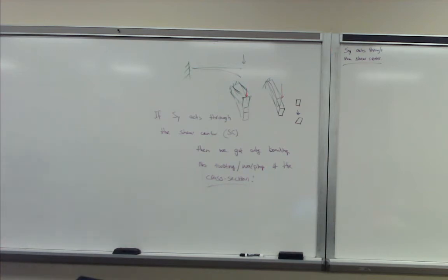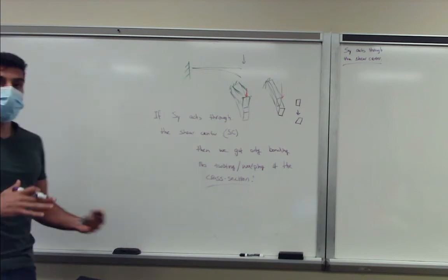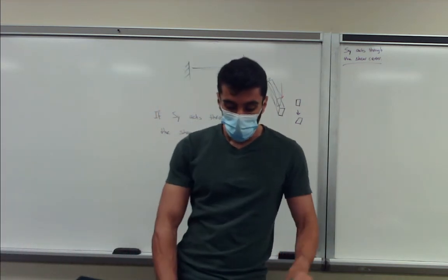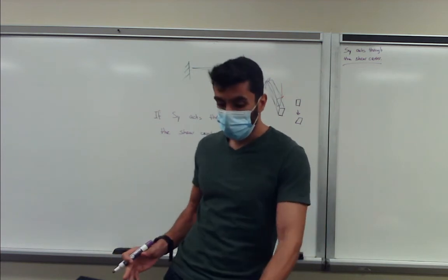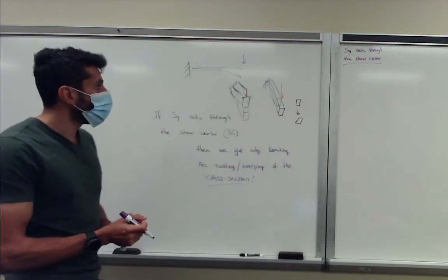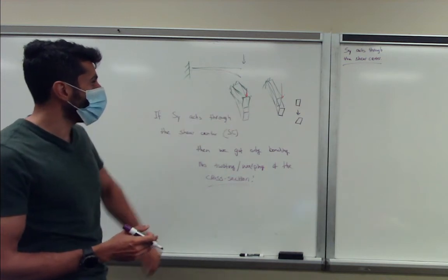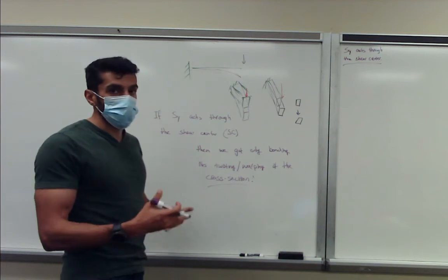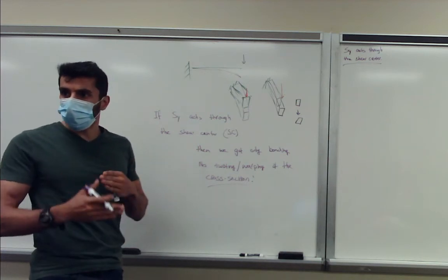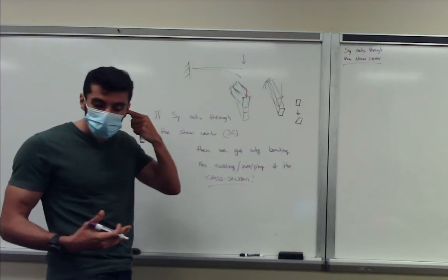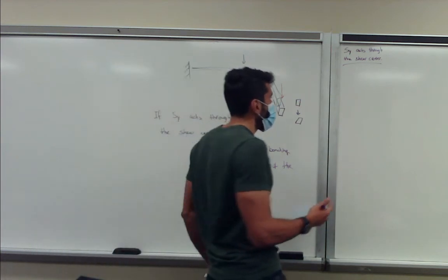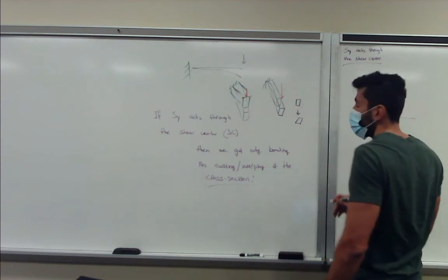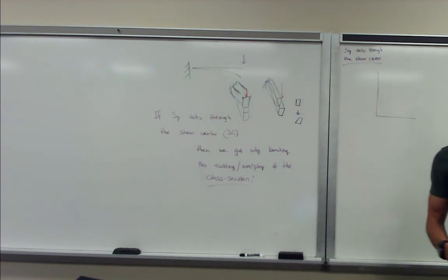So what can we say about shear center? In some cases, we can very easily detect where the shear center lies, and in other cases, we have to determine mathematically where it lies. So from this one, we said if you have an axis of symmetry, this corresponds with it. If you have double symmetry, then the intersection of the two planes of symmetry will also be your shear center. Otherwise, we look at the intersection of the shear flows at a certain point.